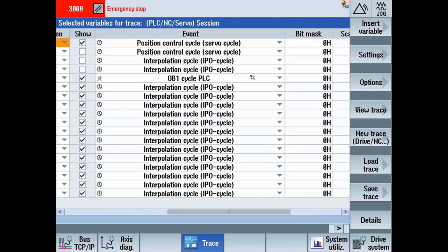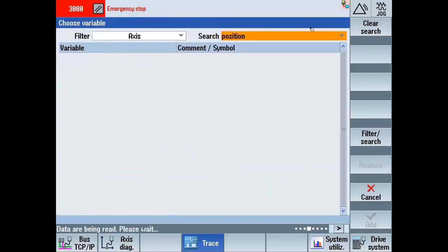So for example, if you are doing a trace like I just did, where we have some PLC state that we're trying to watch, it's entirely possible that I/O state changes happened while you couldn't observe it, even though you may have seen something moving. It's possible the data just isn't observed because you're running at different sample rates. This is also a reason that if you're looking for things such as enable states of an axis, let's say insert variable, and state.